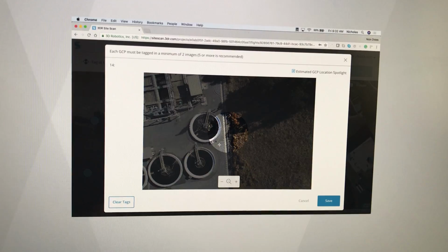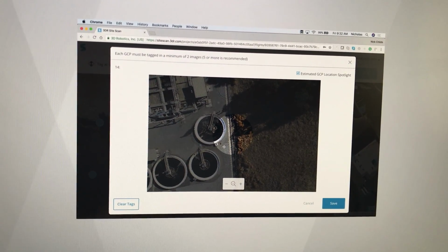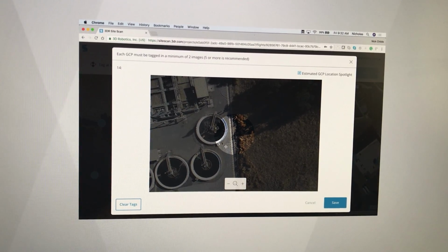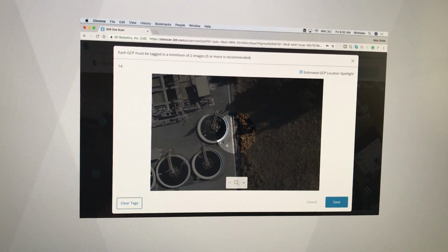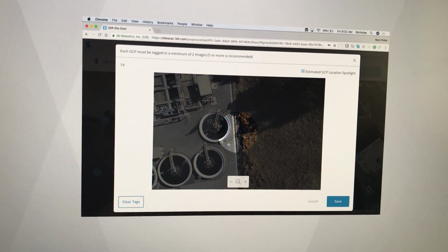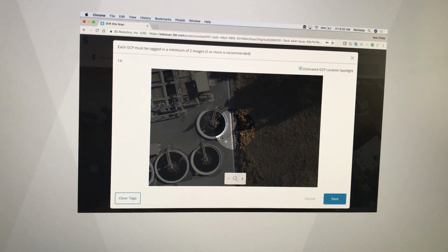But this is what's going to change. Trimble has a product called Catalyst. Catalyst is a small little RTK puck, about $350 or something like that. You connect it to your phone, go out and shoot your point. You connect your cell phone service and it does the correction via cell phone with the RTK system.